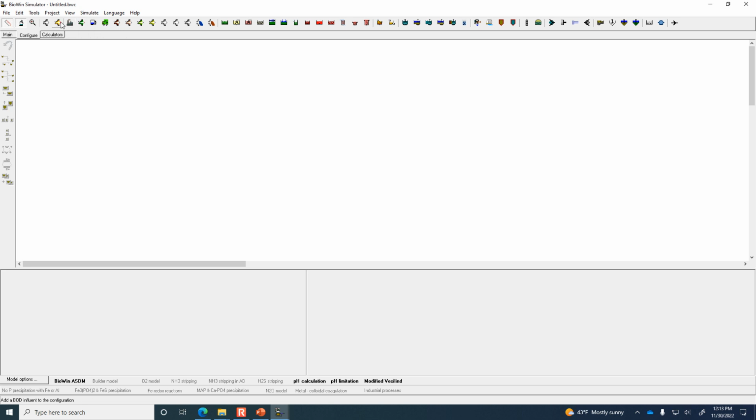So it looks like a pipe that's kind of yellowish and red. This symbol, once you click on it, then bring the cursor down into the main project window, not too close to the top, bring it down a little bit, and then just drop it. So it should say influent, then BOD. The 0 just means that it's the first element that we've created. I don't know why they start at 0, but as we drop additional things, there's a default name and then a numbering. So let's drop that influent BOD, and then back up here to the top.